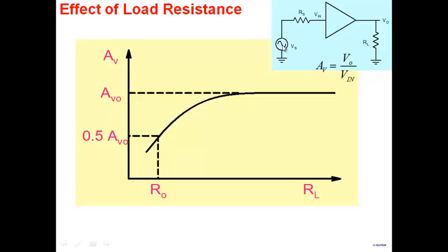This is the signal that we want to be amplified, and the overall amplification is V0 divided by Vs. Sometimes we define V0 by Vs if, let's say, RS is negligible, or sometimes you may also define V0 by Vin, depending on your interest. Obviously the signal of interest is Vs, so V0 by Vs is there. I look at the gain of this amplifier, the overall gain V0 by Vs or V0 by Vin, whatever it is, as a function of RL.